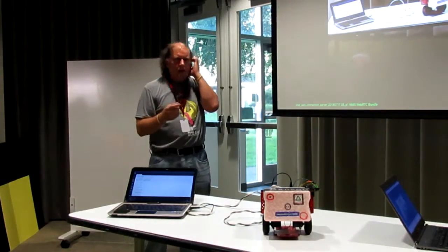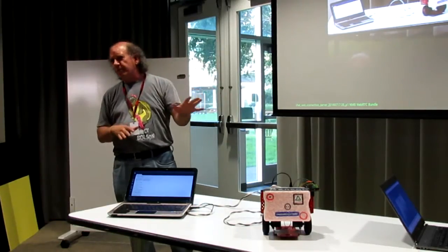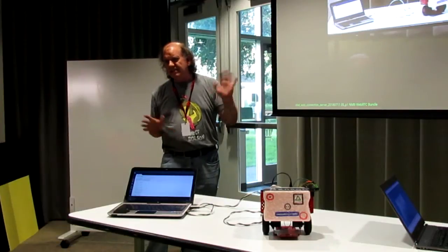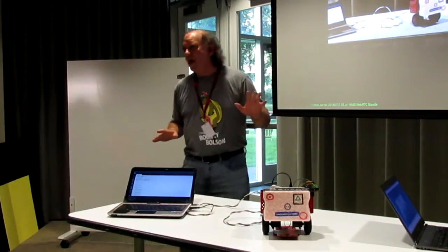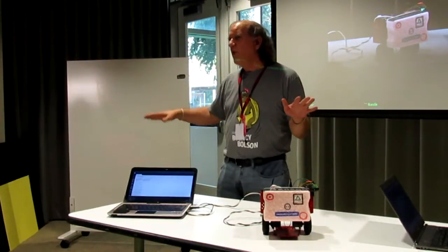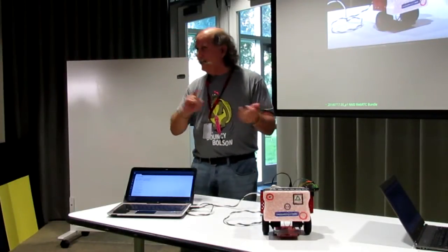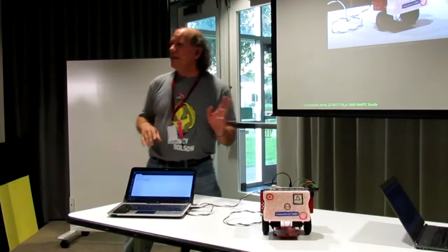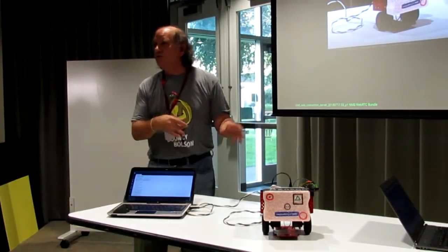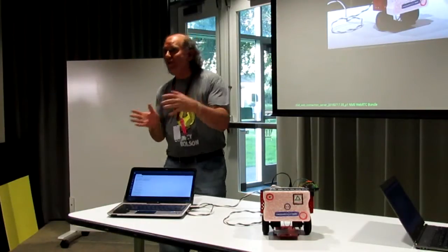What I learned a couple of years ago with the Robo Magellan contest, where you're just sending a robot to a particular GPS coordinate, is it's basically an XY coordinate problem, where you have a target coordinate and you have where you're located, the actual, from the GPS on board. If you subtract the target latitude from the actual: if the target latitude is higher than the actual, you need to go north. If the target longitude is higher than the actual in the western hemisphere, you need to travel east. And so now you know what direction you need to go in, and the GPS gives you the bearing.